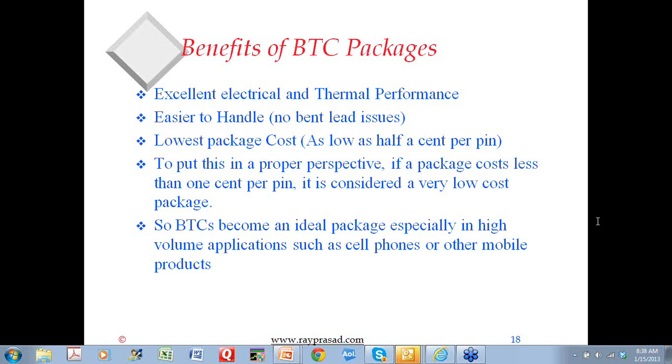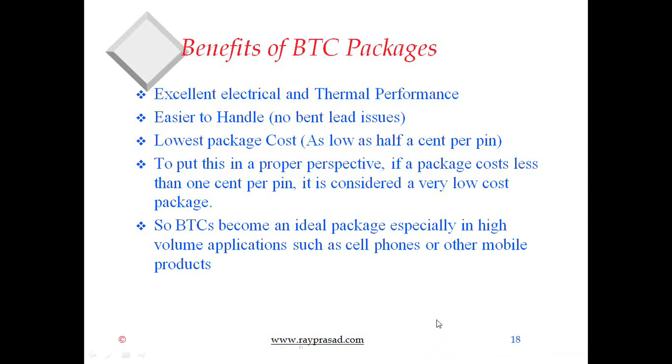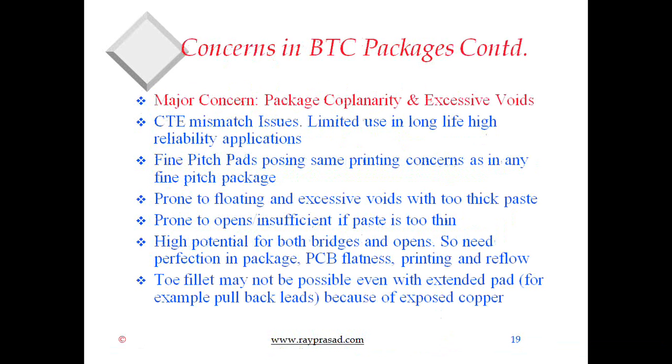So going on to slide 19. The major concern is the flatness of the package and CTE mismatch. So it can be floating, it can be causing voids. So the overall savings that we have because of the lower package cost may not necessarily translate into the lowest cost.